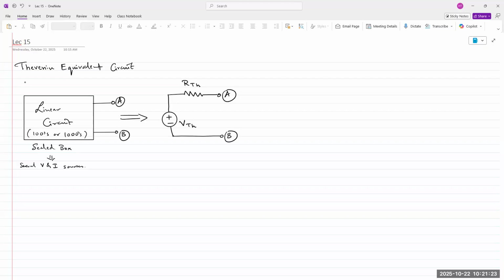Thevenin voltage, again, is something you have done before. You're simply trying to find the voltage between 2 points in a circuit, and you can use any technique you want. You can use node voltage analysis, mesh current analysis, superposition, Ohm's law, KVL, KCL, any of the techniques that could apply for any circuit, and you're simply trying to find the voltage as measured between A and B. So again, very important concept.